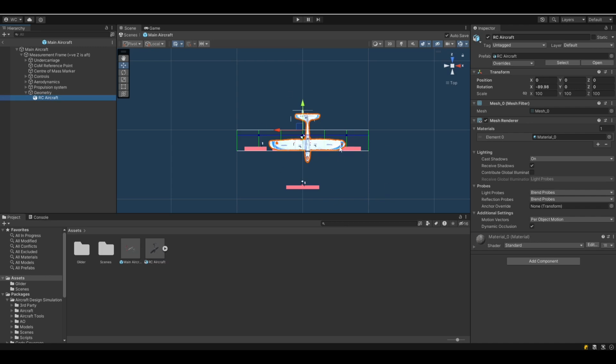And the first thing that I notice is that it's backwards, so I'm just going to apply a 180-degree rotation in the y-axis, like this. My aircraft also has a rotation about X. That's because typically Unity's coordinate system doesn't line up with others, but it applies a rotation to make that work. And then the next thing I need to do is just drag the aircraft so that the leading edge lines up with 0. So something like that should do okay. And that's the geometry of the aircraft imported.